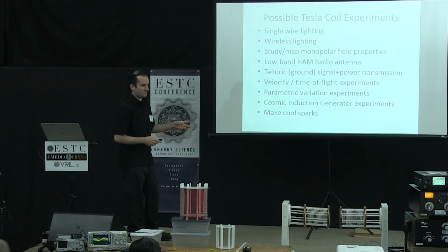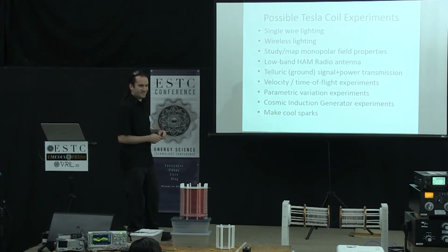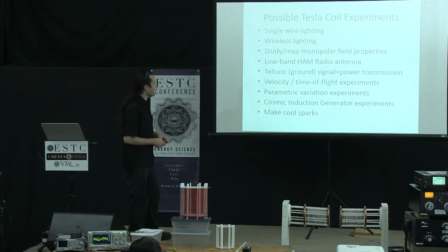And instead of needing the 300-foot antenna, by winding it on the coil, we're able to sort of cheat and work the really low ham radio bands with very little or almost no antenna.